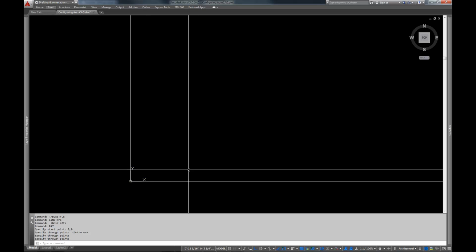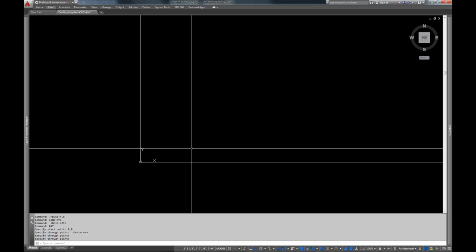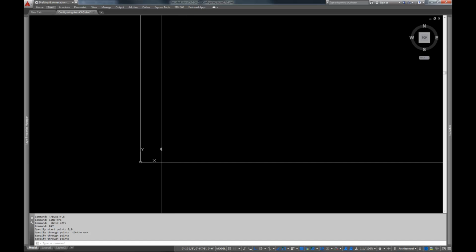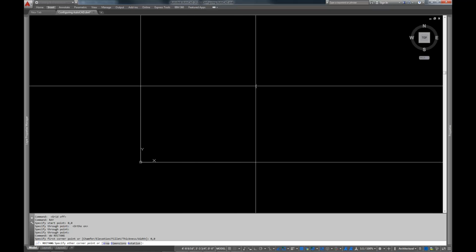In addition to that, you've probably run into this before, where you draw and you hit this issue where you can't pull your drawing board farther than a certain limit, and you can reset that really easily by making a shape that extends beyond those boundaries. So for example, let's go ahead and make a rectangle. I'm going to start it at 0,0, and I'm going to make it 300 feet by 300 feet.